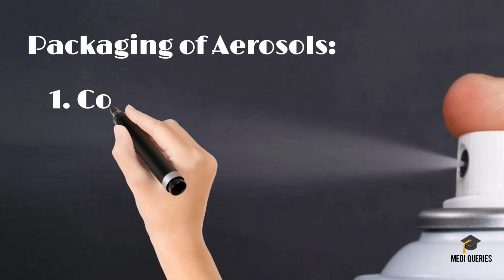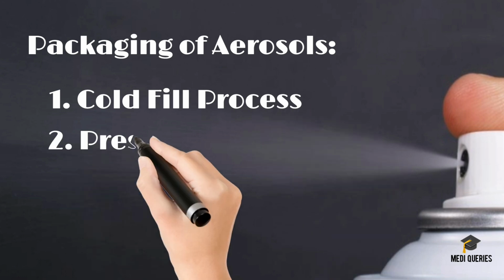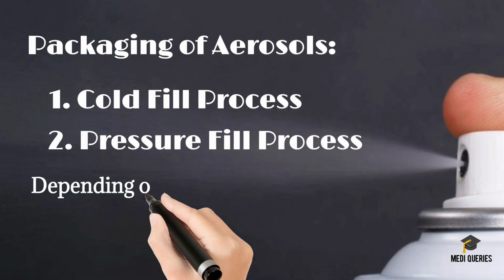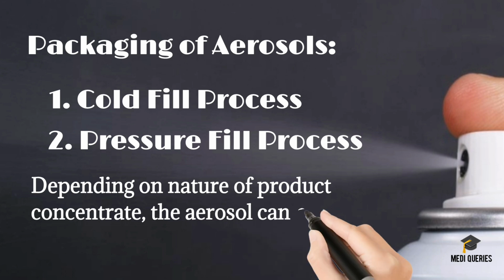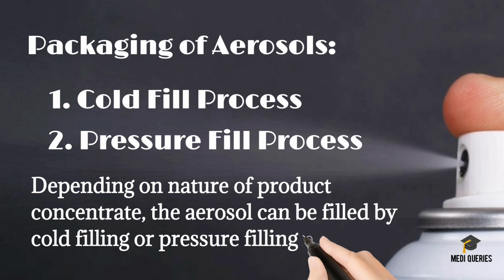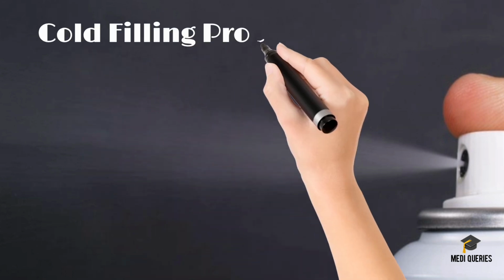Packing of the aerosols. The aerosol products can be filled in two ways. The first process is the cold filling method, and the second one is the pressure filling method. We will see them one by one. Depending on the nature of the product concentrate, the aerosol can be filled by cold filling or pressure filling processes. So the first process is the cold fill process.